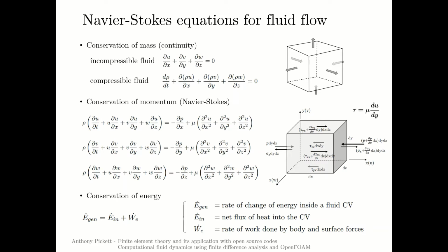If it's an incompressible fluid, in this case, density does not change, and our conservation law is given here. So if you think, for example, du/dx is the change in flow in perhaps this direction, if there is an increase, then it will have to be balanced by changes to these other flows, such that the sum of them is always equal to 0 for no increase in mass.